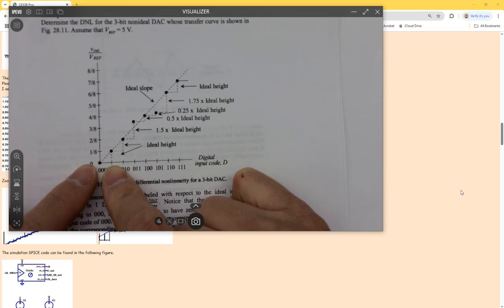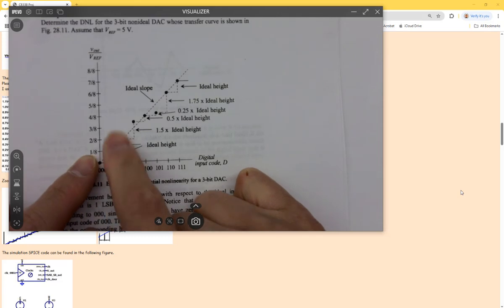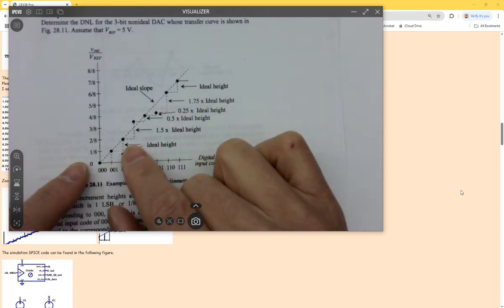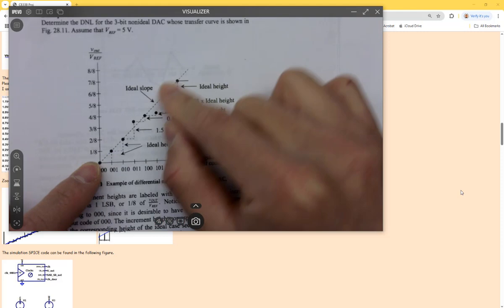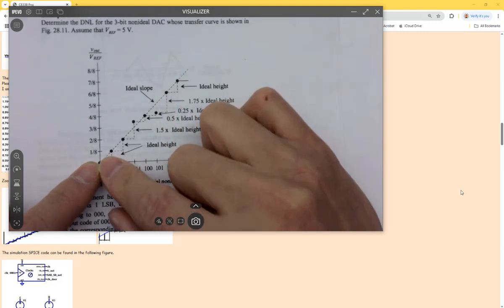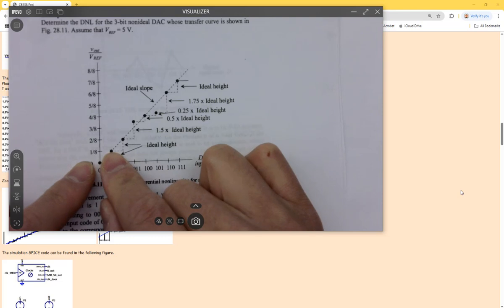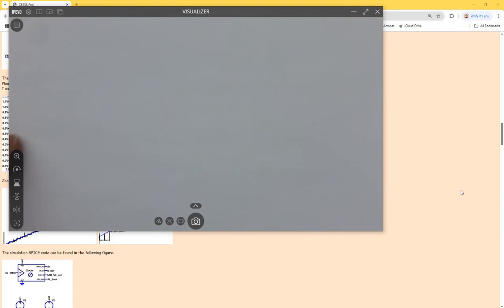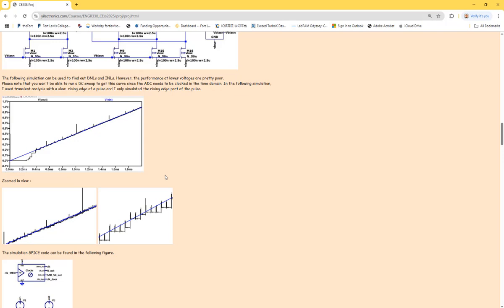That's for the ADC. But as for the DAC, you can see whenever it reaches the next step, it should jump to another value. And we're going to get into the details today, every single detail about how to calculate it. But you can see that the straight line here is the ideal value. And all the stairs are the ADC or DAC's output. They are stairs. In that case, there will be errors because it's not perfect resolution. So eventually there will be errors.